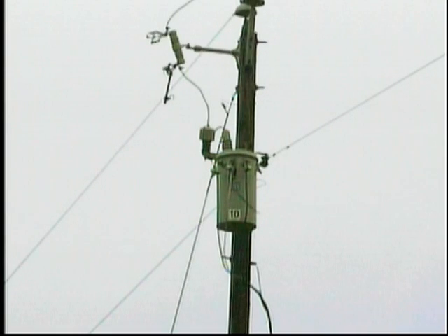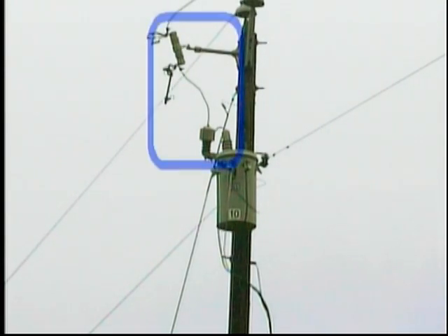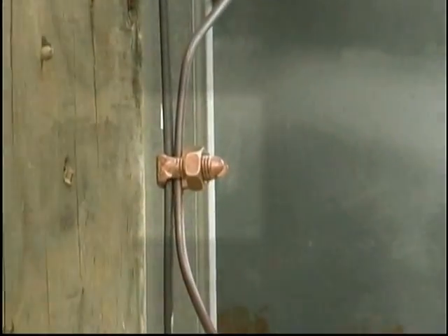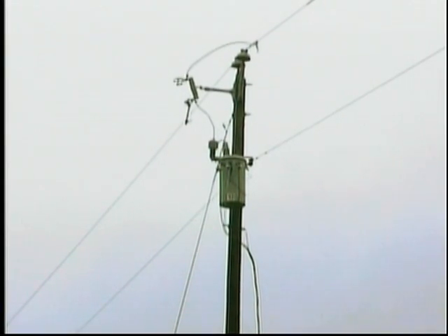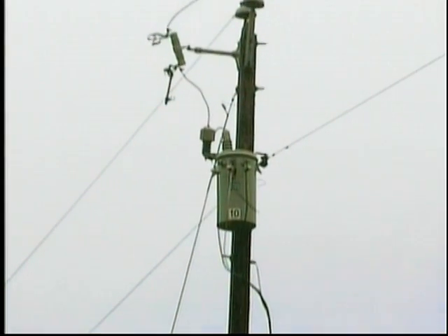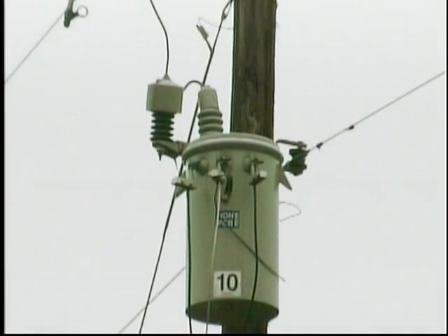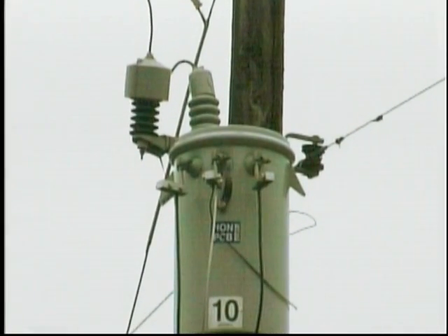In the field, a transformer connected to a Y system looks like this. In this example, the H1 bushing on the transformer is connected to an individual phase wire. The case ground on the side of the transformer is connected to the grounded system neutral. Provided that the primary winding of this transformer is rated for the phase to neutral voltage of this Y primary system, the transformer should function properly.